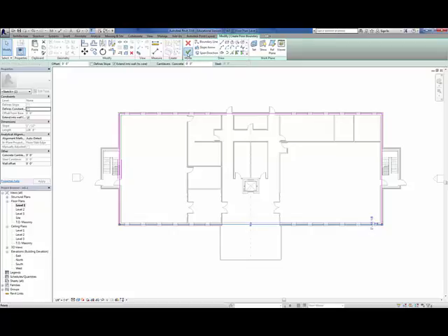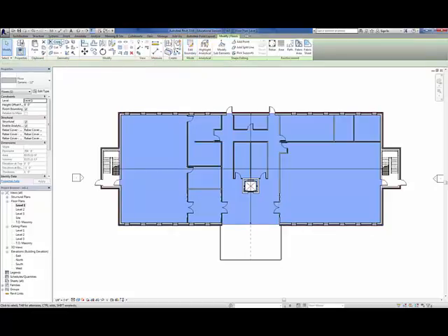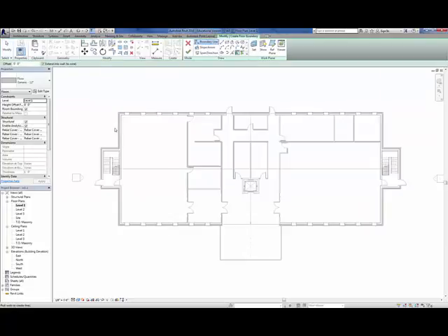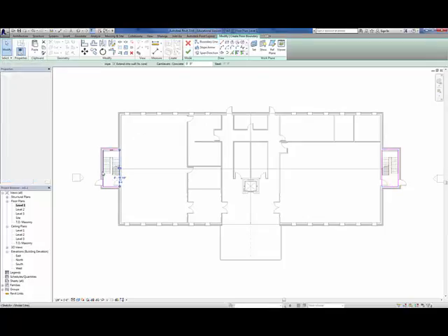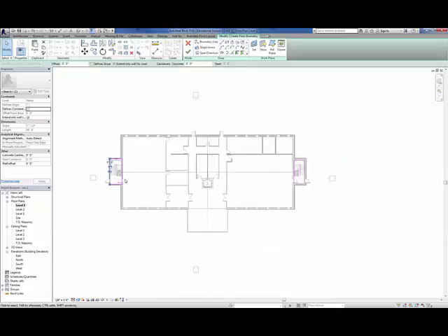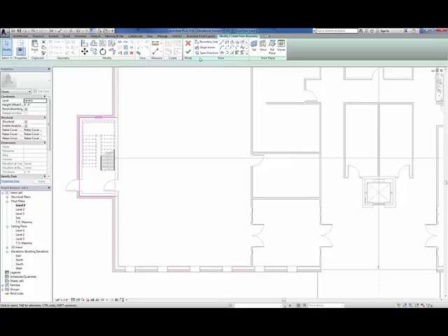So let's get this here. I'll do another structural slab. This time I'll come in and I will pick the stairwell. Okay. And on this wall, I'm going to flip that one. Sometimes it gets a little picky when it's doing these, so we have to go in and actually tell it which side we want that on. Or if it's being a real pain, we just go in and we draw it in where we want it, which does have to happen from time to time.